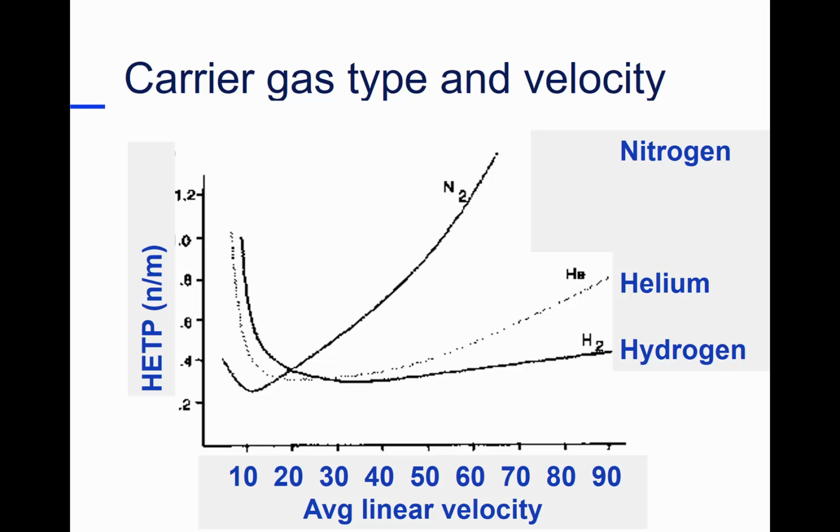So it looks like, generally speaking, the heavier the gas is, the less efficient it is when you have a higher flow rate. Is that just due to atom size, or is there some other reason? Why is your question? It deals with viscosity of the gas primarily. These are very, very low viscosity gases. And so their flow properties in that column are quite different than a high viscosity gas. That's the major factor that goes into that.